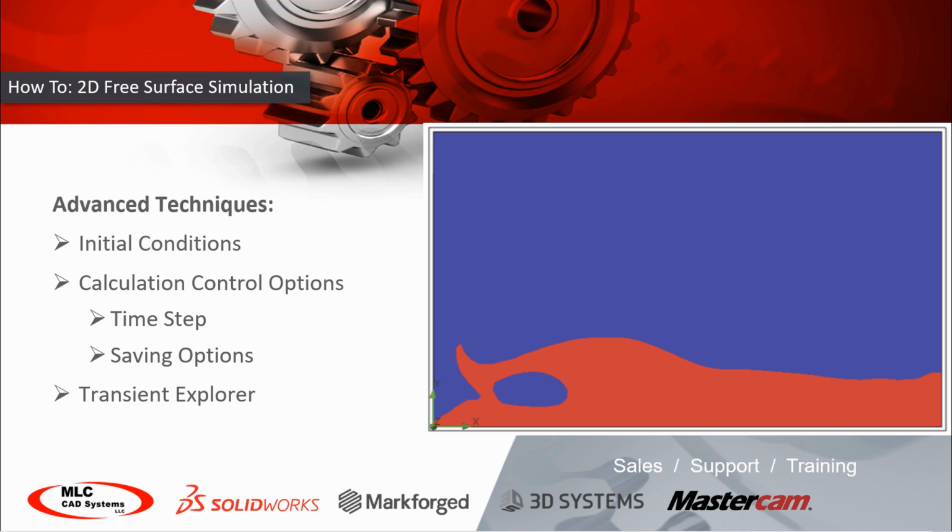The other thing I got into was the calculation control options. And that's right-clicking on the input data folder. You can find those. There you can set up your time step, your saving options, your finishing condition. That's where you could turn on solution adaptive mesh refinement. So those are those deep down controls.